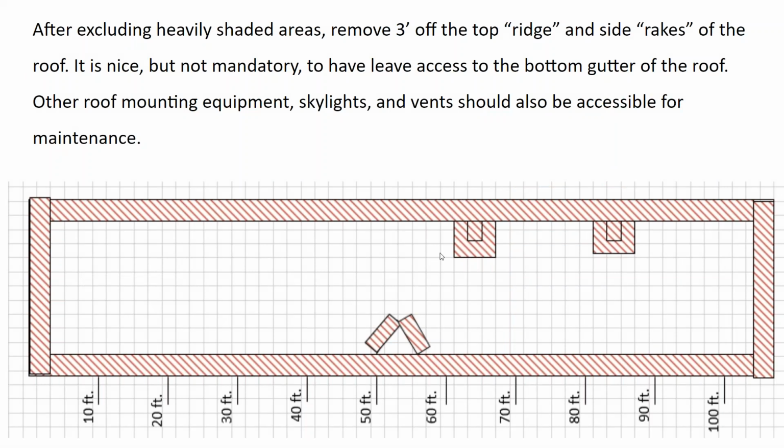And the other thing to know is slanted commercial rooftops, which don't have workers on them for service and maintenance, generally will follow the residential guidelines of the 3-foot offsets, whereas commercial flat roofs, and sometimes residential flat roofs as well, will have much more stringent setback requirements: 6 feet from the wall, 4 feet from electrical equipment, for servicing purposes and for safety reasons.